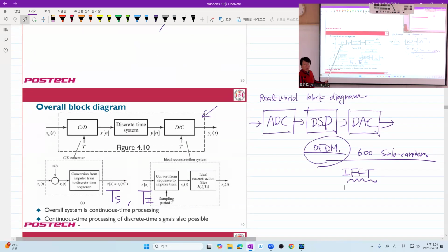The problem is that, mathematically speaking, in order to have the same information here and there, what do we need about this one? We need this signal strictly band limited and our sampling rate greater than twice the maximum frequency content. What if that is not met?